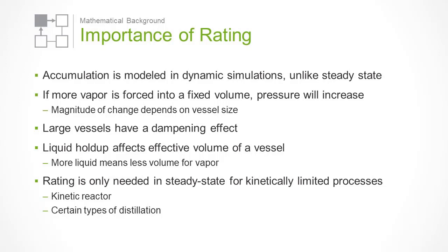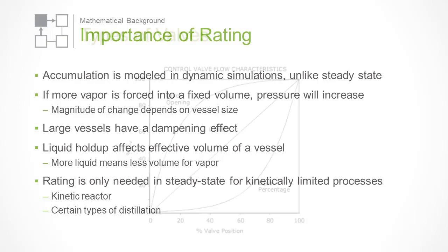In dynamics, vessel rating matters, and it can have a large effect on the performance of your process. In steady state, equipment sizing is not required unless you are modeling a kinetically limited process, like a kinetic reactor or certain types of distillation. In dynamics, it is important to select proper equipment sizes. Equipment sizing will affect holdup, process response time, and pressure drop.